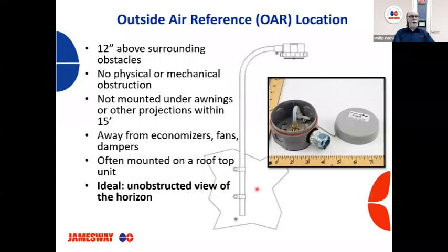So just to get it up there, I just want to mention, sometimes I'll go to hatcheries that we feel like the pressure is not being monitored correctly. So when we examine these, sometimes insects, spiders can get inside and build a little nest in there. And so it's good whenever you're doing periodic preventive maintenance to check these for any type of thing that may be stopping it up or preventing it from measuring air properly.